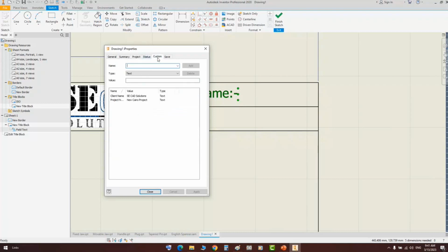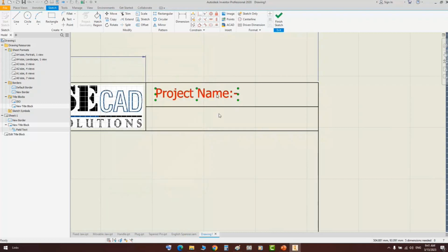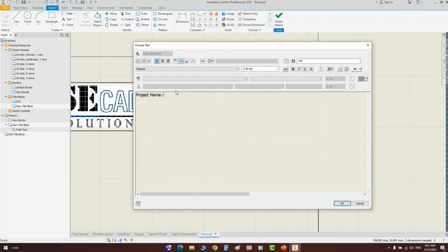And if you would like to create a custom property, we discussed how you can create a custom property. So from here, let's come back again and add a custom property. So from here, let's select custom property for the drawing. Here you will find the attributes or parameters that you generated, like client name and project name. Let's select the project name, and by clicking on this button, which is add text parameter here, you can figure that you have a new parameter.